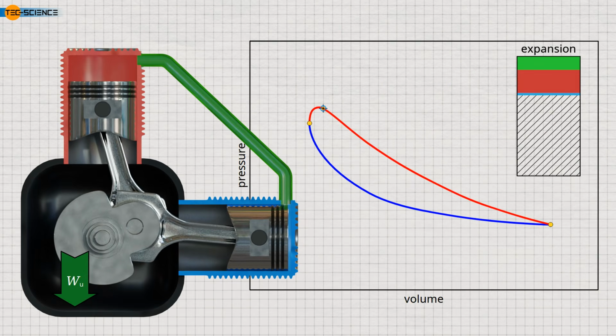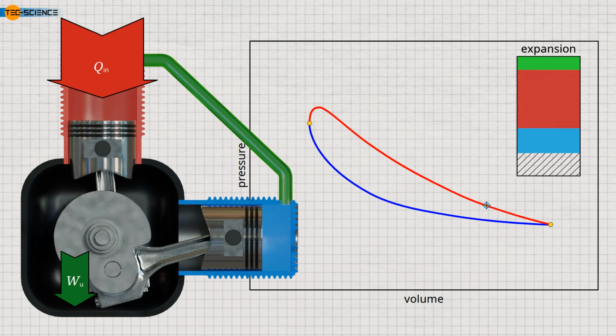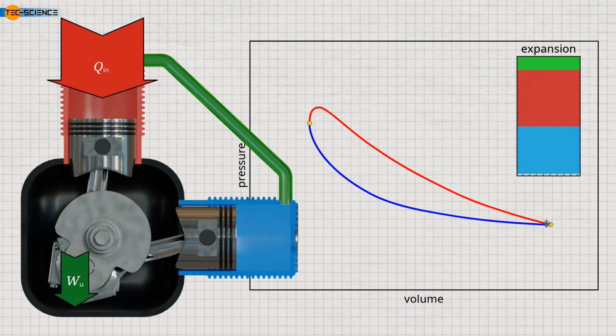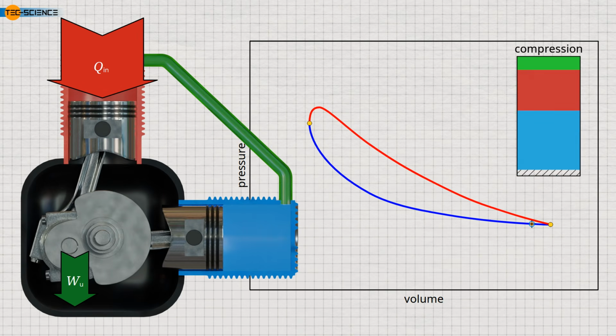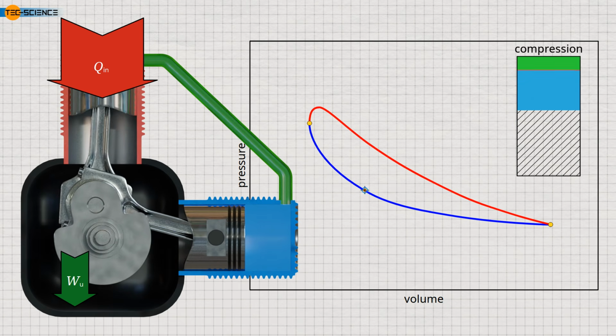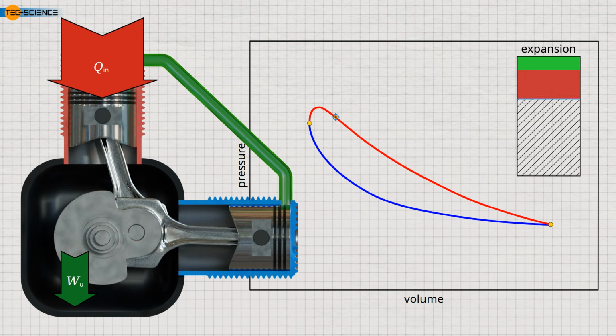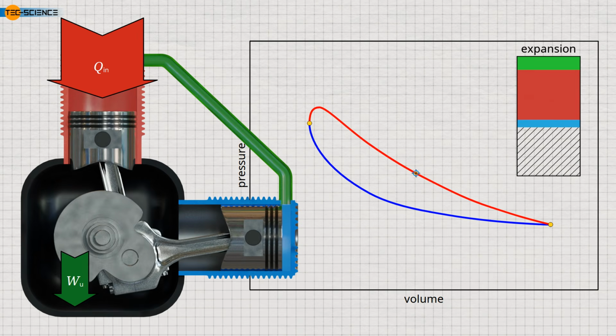The useful work comes from the heat input of the heated cylinder, which transfers heat to the expanding gas, thus ensuring an increased temperature. Note that the temperature of a gas normally falls as it expands. The cylinder must therefore be heated to keep the temperature elevated. Not all of the heat supplied to the engine can be converted into useful work.